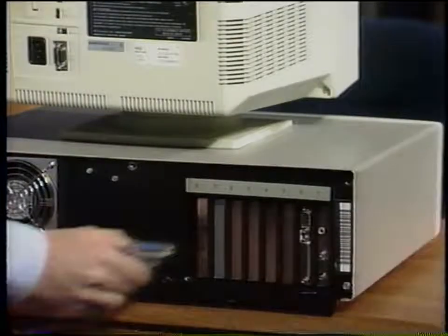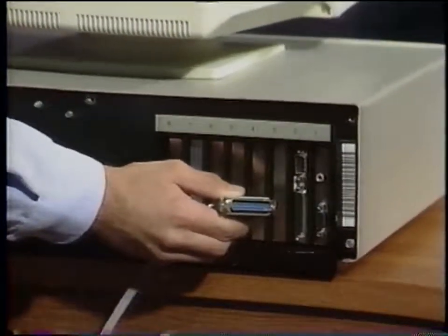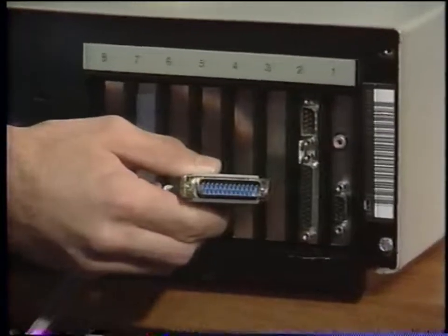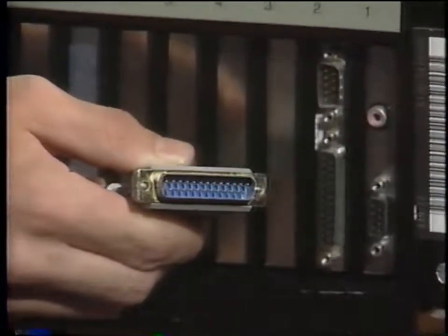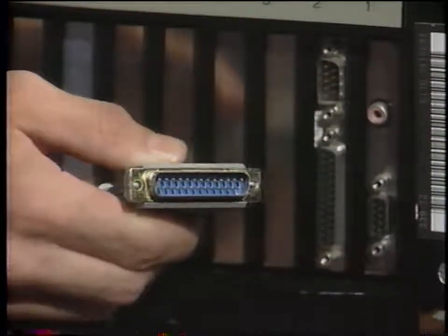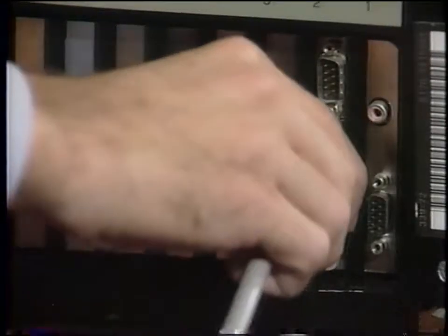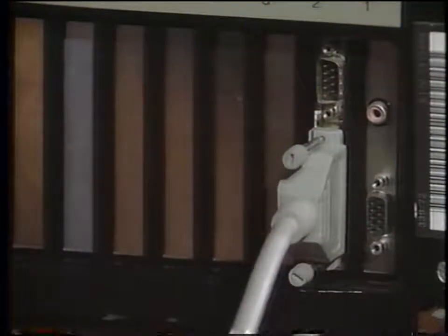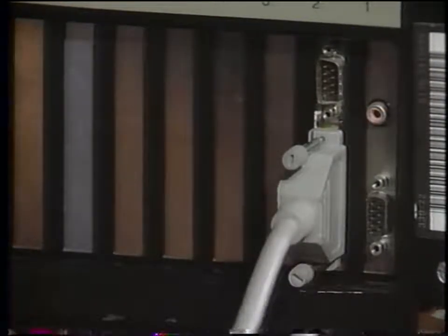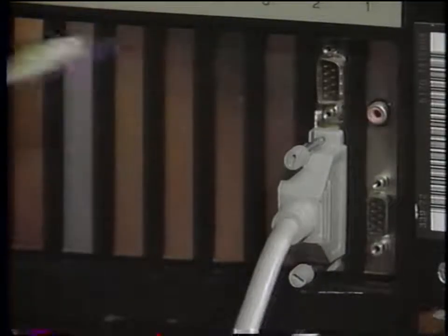The other end of the connector looks like this. It's commonly called a male DB25 because it has 25 pins sticking out of it. You'll need to locate the female connector on the back of the system unit to connect this to. If you find more than one, connect it to one or the other, and you can test it later. To connect it, you need to carefully push it onto the connector and tighten the two screws which secure it.